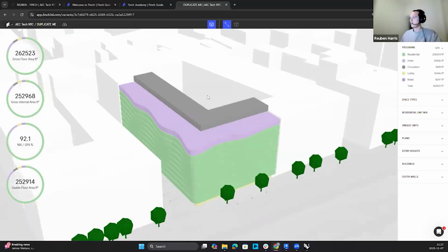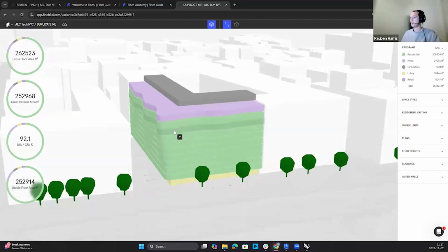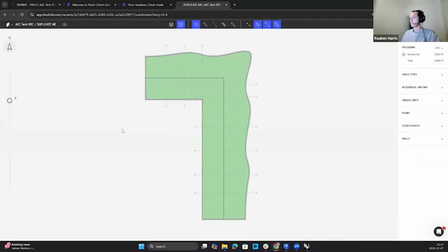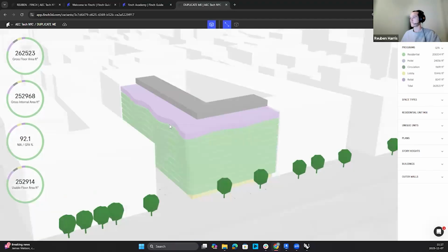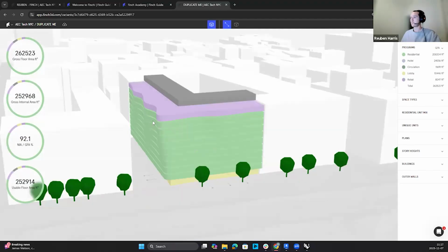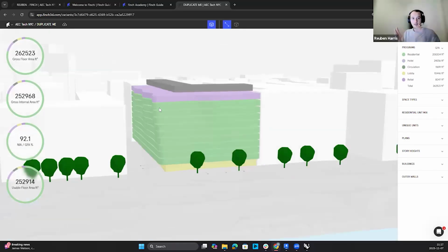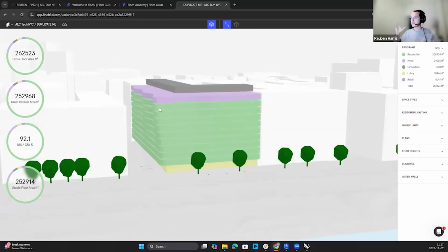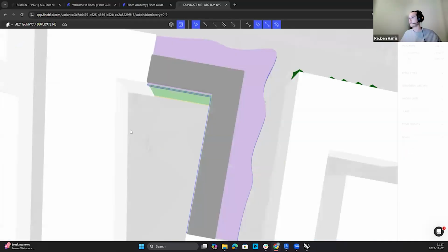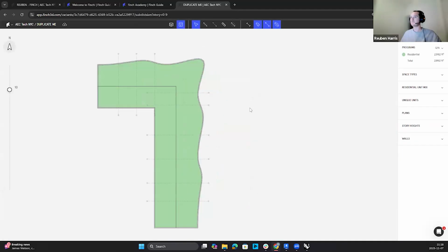Okay. I'm going to ask everyone now to dive into the next studio in Finch. To do that, we're going to double click on one of our floor plates. I suggest we work at the top here because with this undulating facade, it gets smaller as we go towards the ground floor. If we start at the top, that means that when we copy information down, everything's going to land really neatly. So start with one of these floors, the 10th or the 11th floor here.